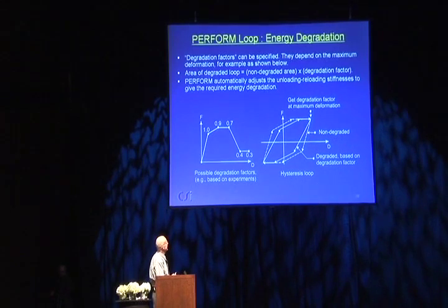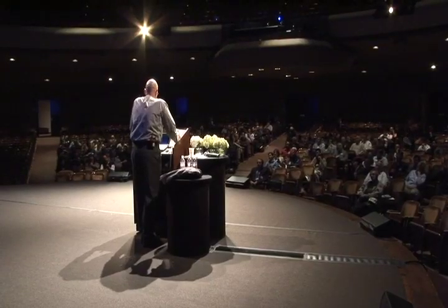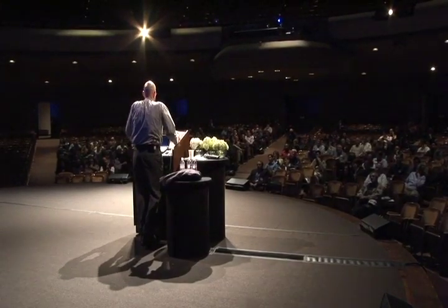If you go out to the L point, maybe 0.7, here 0.4, here 0.3, you get to pick your own numbers. I was talking to somebody earlier about the coupling beams in the example structure we looked at in the last session, and what was used for those coupling beams was a factor of 0.15 for basically all displacements.